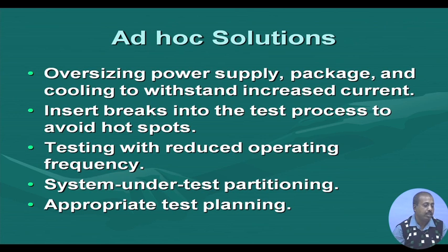Another solution is to insert breaks in the test process to avoid hotspots. If the circuit is tested continually, and if one region of the circuit is excited throughout the test session, then that part will become hot. So, that creates some hot spots in the circuit. So, what we do, we break the test session.